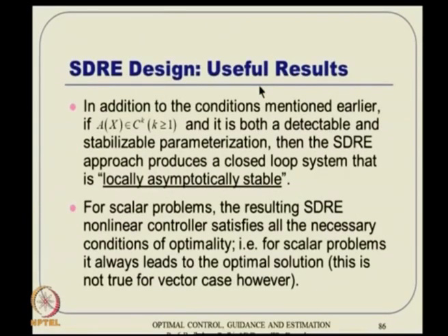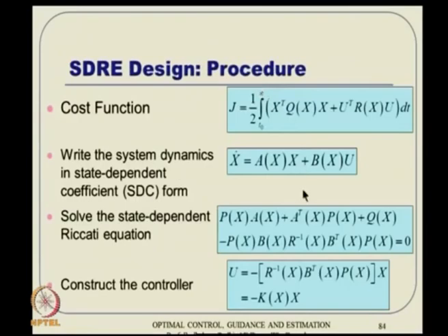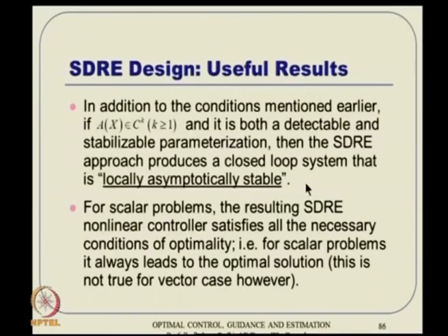Then SDRE results: not only is it intuitive and hence elegant for implementation, but it is also backed up with some nice analytical theoretical guarantees. One of them tells that the LQR solution is always guaranteed to be locally asymptotically stable. And for scalar problems, it is guaranteed to be optimal. That is what these theorems tell.